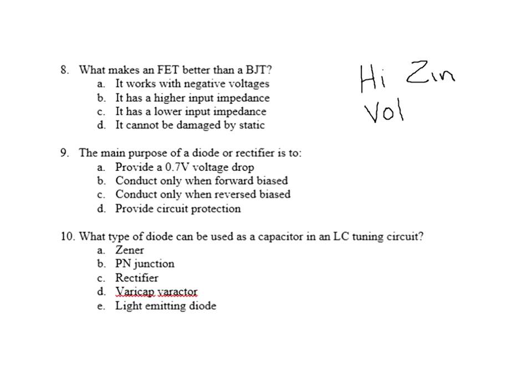Let's see if we can find out which one of these will work. Okay. Did we say anything about it working with negative voltages? Well, it does, but so what? So does a BJT. Does it have a higher input impedance? Well, that might be a good answer, but I'm not just going to answer that yet because I want to look at the rest. Can an FET not be damaged by static? Hey, I didn't tell you this, but FETs, especially MOSFETs, can easily be damaged by static.